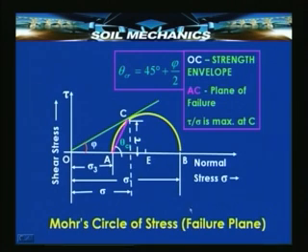Go to the Mohr circle, find out at what point tau becomes equal to sigma tan phi. Plot the normal stress, choose the origin, plot the vertical or shear stress, choose the point E, which is the center of the Mohr circle. Plot only half the Mohr circle for convenience and clarity with EA as the radius. We know sigma 1 and sigma 3. So, we get the Mohr circle.